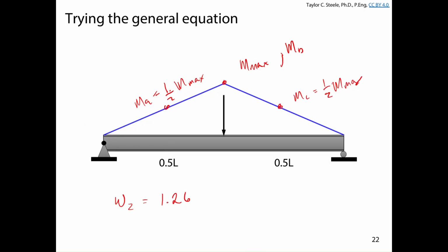So this is a little bit of dialogue that might not be necessary, but if we have a point load P that moves along the length of the beam, some kind of crane carrying beam, where is the point load going to be when the moment is maximum? Or what position of that point load will cause the maximum moment on that beam? Well, I hope that everyone remembers that if we put the point load in the middle, that generates the maximum moment, right?